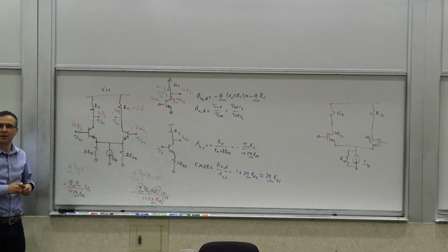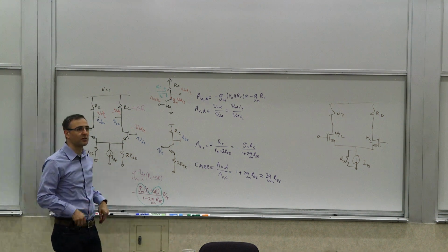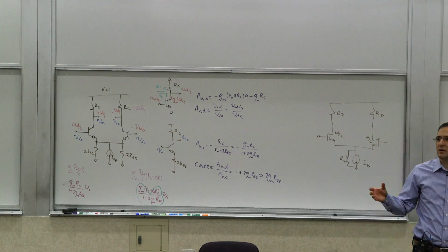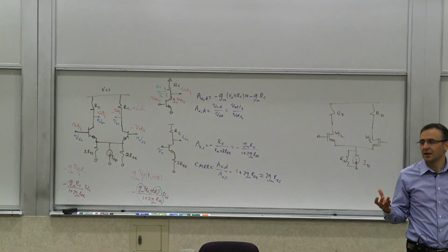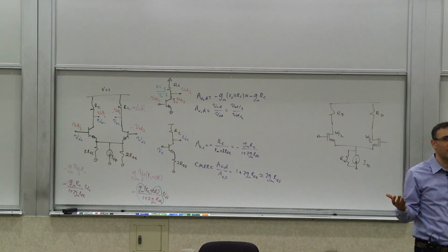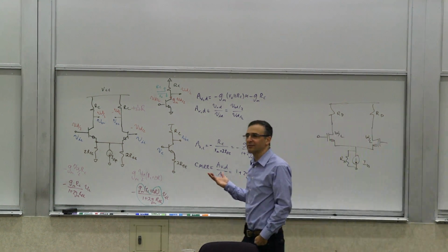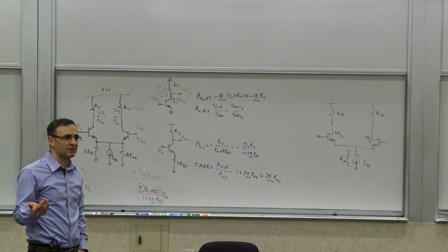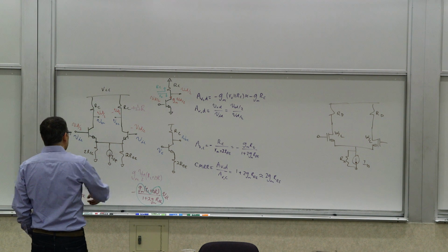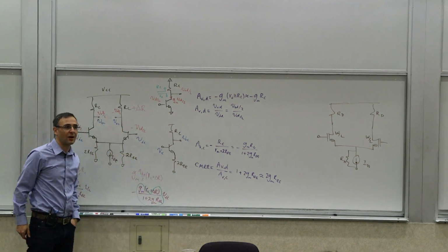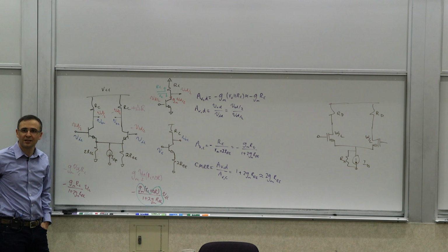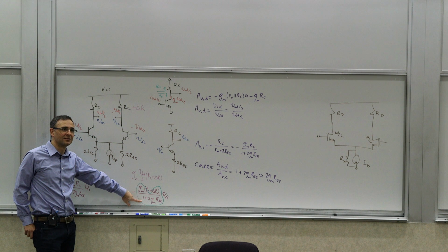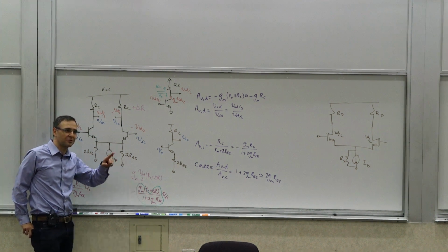Right? This is called common mode to differential conversion, because basically the mismatch has converted your common mode to differential mode. And once it's converted to differential, you can't get rid of it, because the circuit cannot differentiate between them. It's already become part of your signal. Now, it is still attenuated by that factor, the common mode rejection ratio, essentially, right? But it is there. And that's why common mode rejection ratio matters, because it even appears here in that conversion. Did I answer your question?